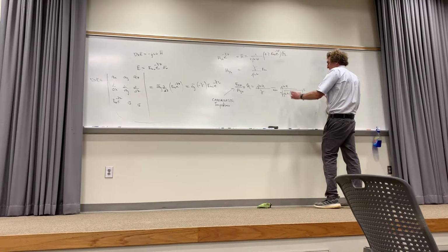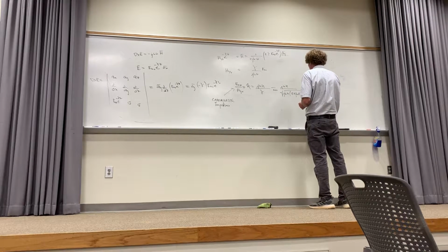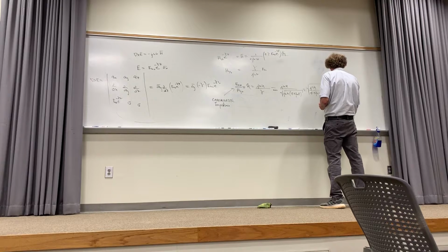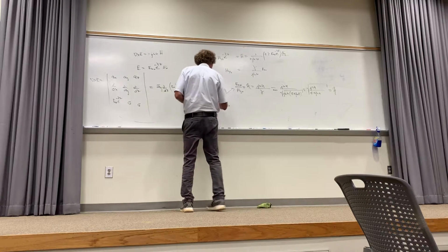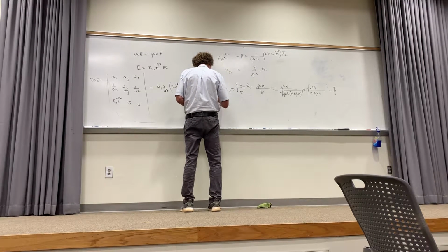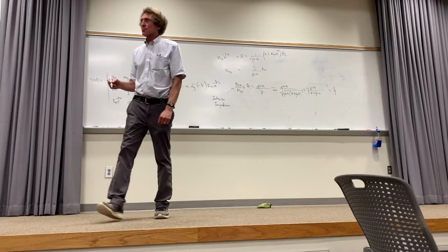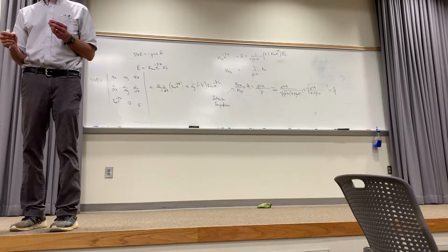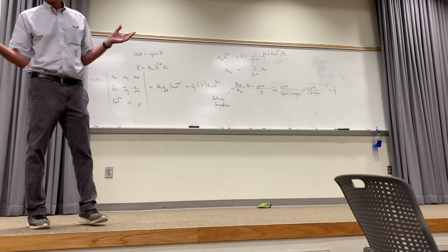Now I have j omega mu to the single power over j omega mu to the 1/2 power. I can rewrite this as the square root of j omega mu over sigma plus j omega epsilon, and that is the intrinsic impedance. This is equal to eta. Characteristic impedance is what you use for waveguides; this is intrinsic impedance. The word intrinsic implies it's a property of the material at a point. If you look at characteristic impedance of a waveguide, it has to do with bulk parameters, overall.